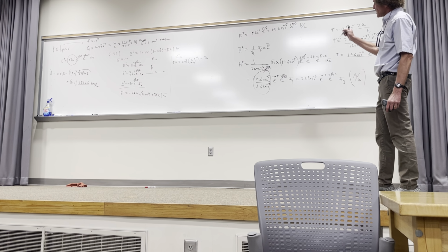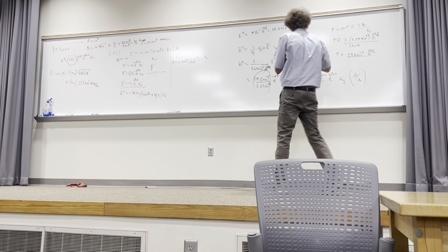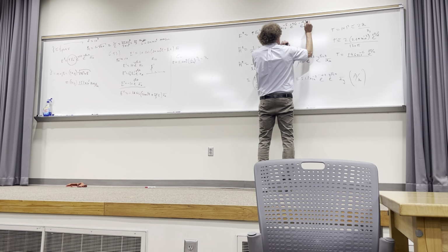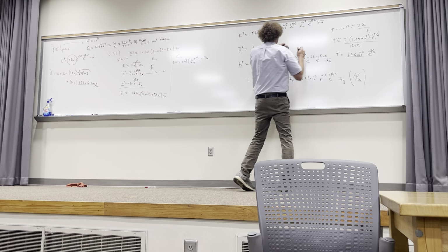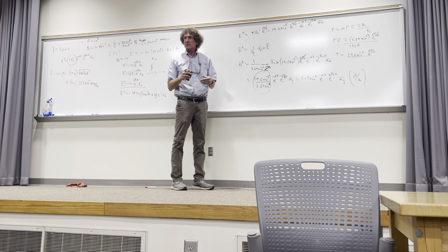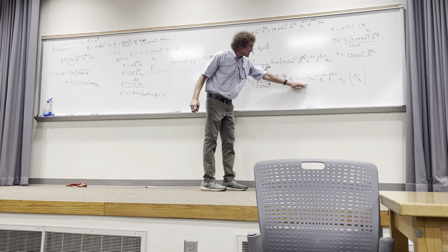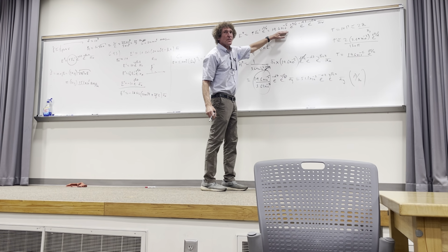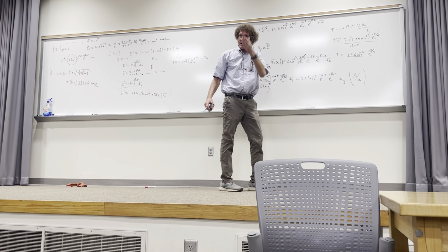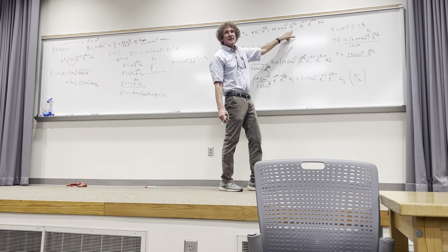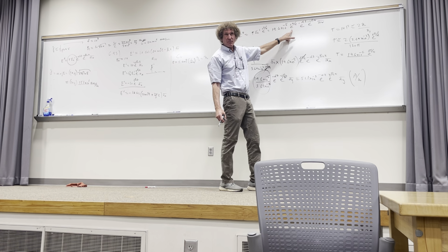Now, the E field in the phasor domain, I didn't put the complete statement here, but if I wanted to, I would have to put e to the minus alpha z times e to the minus j beta 2z here, and it would be ax. Do y'all follow me? To make it also with the distance variation, right? Now please watch this. When you look at these two, you'll see one thing that's apparent. They both vary the same way spatially, right? They both have the exponential decay and the same beta, correct? But this has a 45-degree phase difference. Do y'all follow me on that?